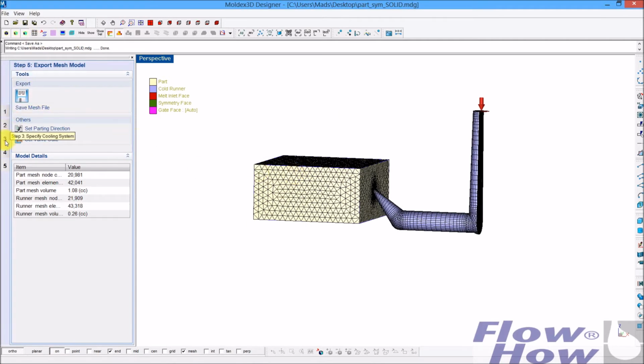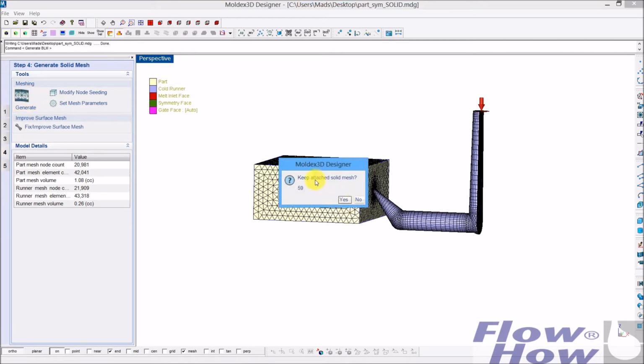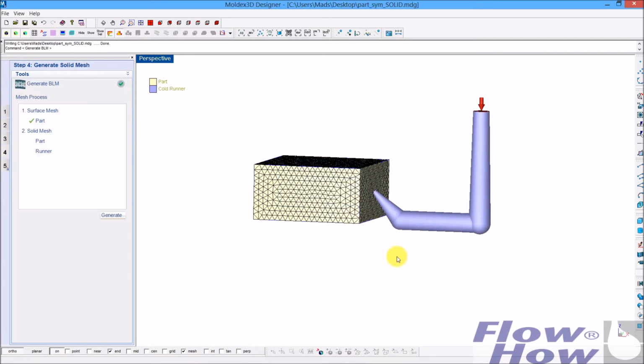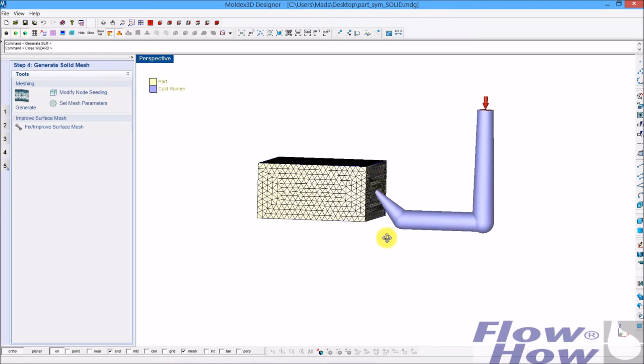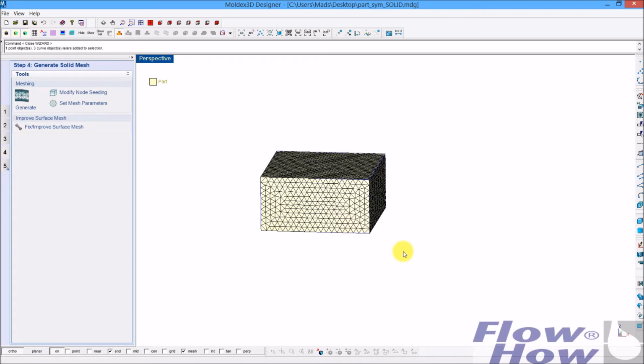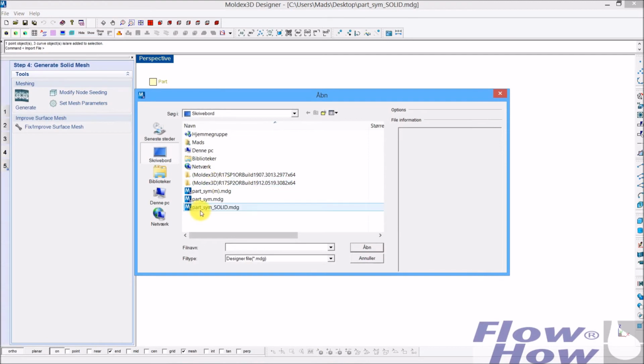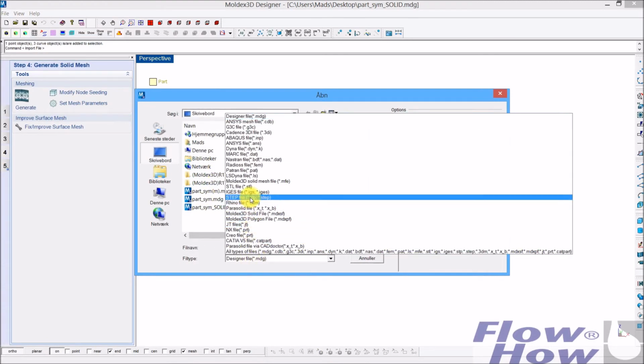And I want to get rid of the mesh. The easiest way is just go into generate, keep attached solid mesh, no. Then it's gone. And I'll delete these things away with the lines, and I'll import step file.